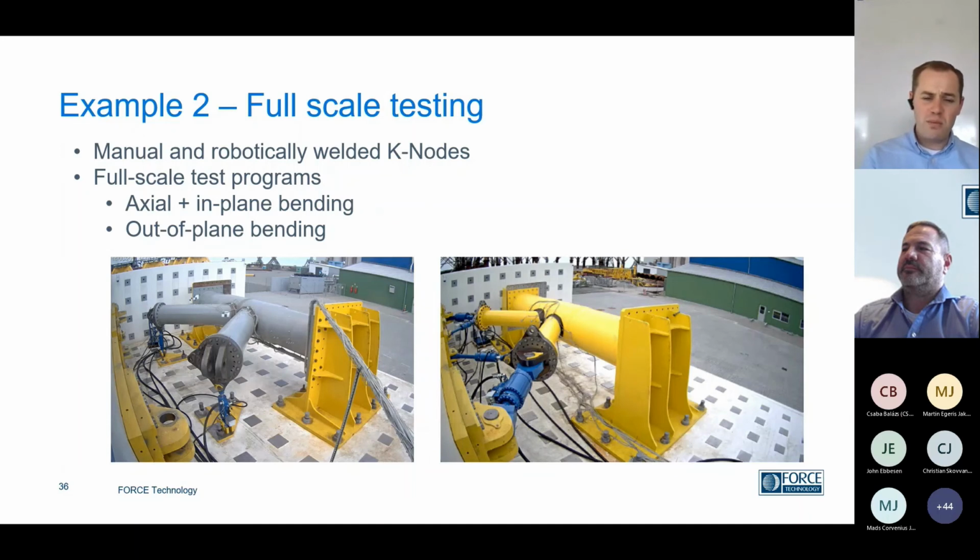In these programs, we were able to run 1 Hertz, and we had fatigue lives over a few million cycles in some of these specimens. So we were running for many months, which is, in some regards, quite a contrast to the fatigue programs we saw on the test machines, where on some of those machines, as I said, we can run around 100 hertz. That's getting us 10 million cycles in roughly between 24 and 30 hours if we're running those high cycle test machines. So just to give a quick picture of some fatigue testing in real life.